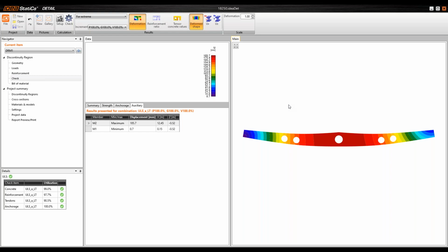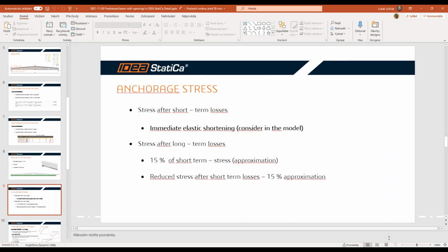So it's on the 3rd or 5th day, but on these days the concrete strength and also the modulus of elasticity are totally different, because this is a time dependent material, and so it's more than recommended to change the material properties. How to do that? Let me come back to the presentation.